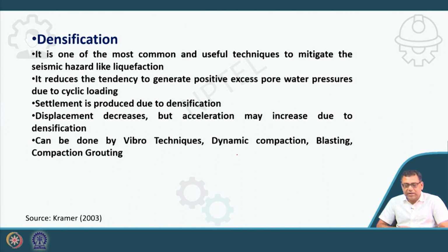It reduces the tendency to generate excess water pressure due to cyclic loading, because the amount of voids is being reduced. So, the tendency of positive excess water pressure due to liquefaction will reduce. Why? Because if we densify the soil, if it is in a loose state, it can go to dense or moderately dense.